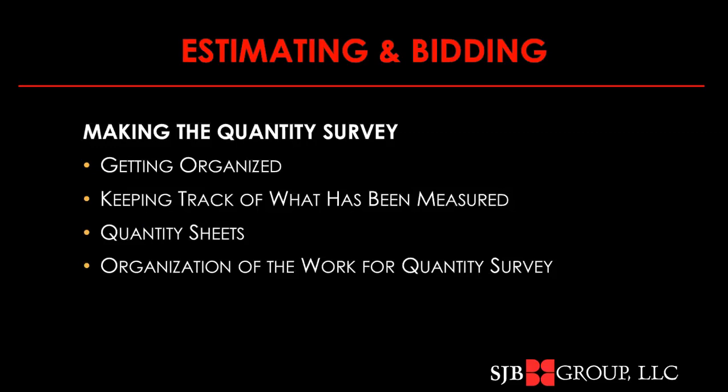For example, next slide. Make standardized forms for use on each and every one of your estimates to help with the consistency. Do your quantity takeoff work on the quantity sheet. Those answers get carried into the cost extension sheet where some additional costing gets done. And the bottom line on the cost extension sheet for a given pay item gets carried to a recap sheet. Next slide.